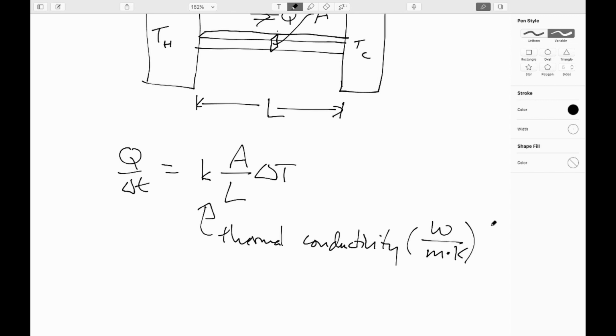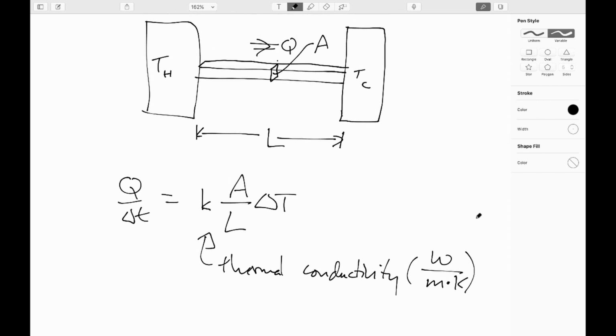Sometimes, instead of thermal conductivities being quoted, they'll quote what are called thermal resistivities. This turns out to be the reciprocal of the conductivity. For instance, when you're buying insulation, the R values are the thermal resistivities. However, they're given in English units rather than metric units.